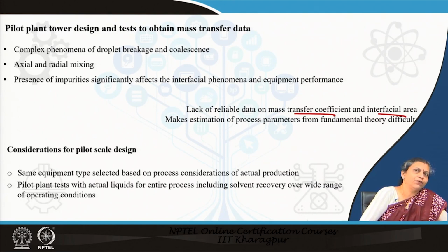Now, when we perform the tests in the pilot plant, two things are important that we should remember. First thing is we have selected the contactor earlier itself. So, therefore, the pilot plant tests have to be conducted in the same equipment type based on the process considerations of the actual production. If we plan that, well, for this particular case we would have to go for a packed tower contactor, the pilot plant data will also be collected in the packed tower.